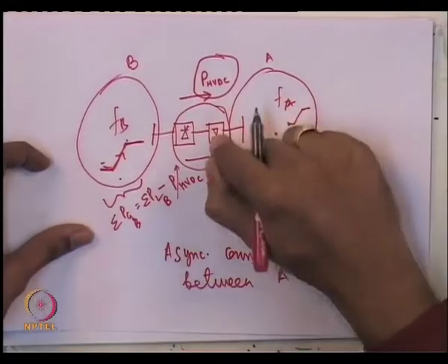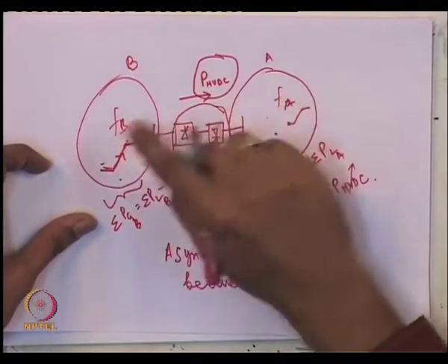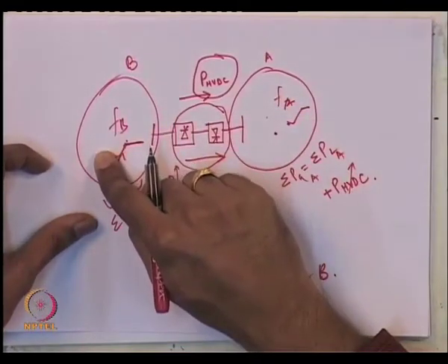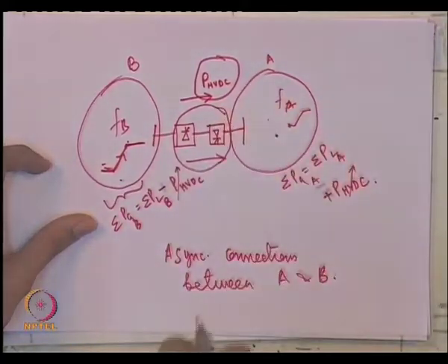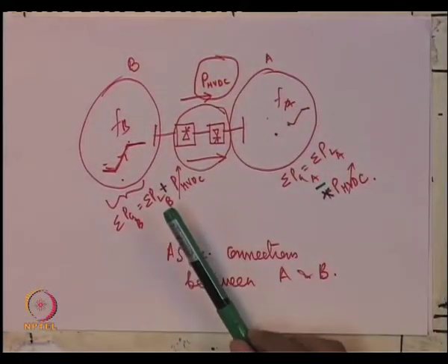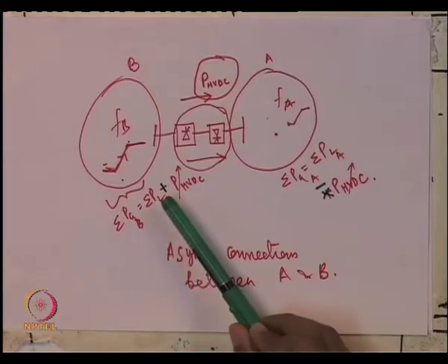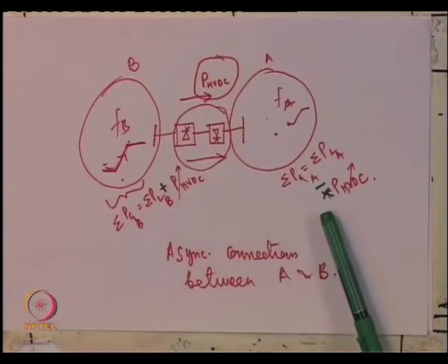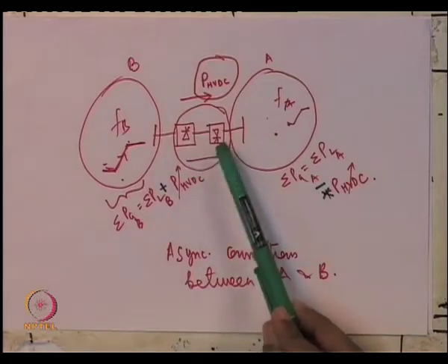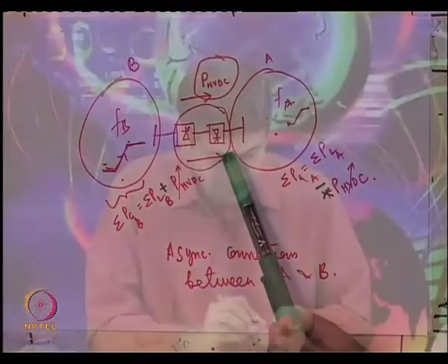You can use HVDC power to equalize or slightly help one region by changing the HVDC power. Please note that there is a minor error in the sign here. This should be positive here and negative here, if the direction of HVDC flow is as shown in the figure.